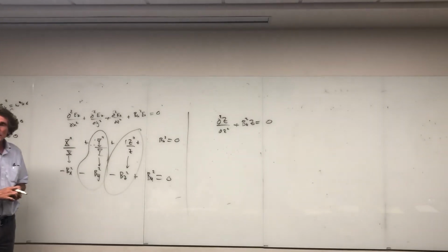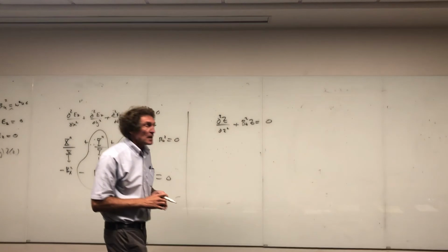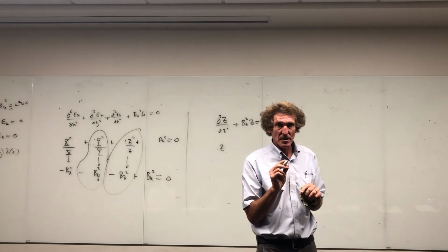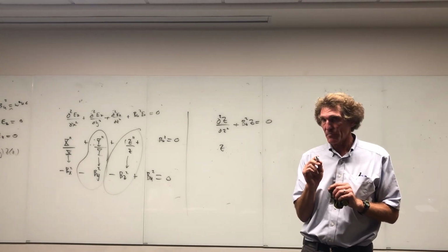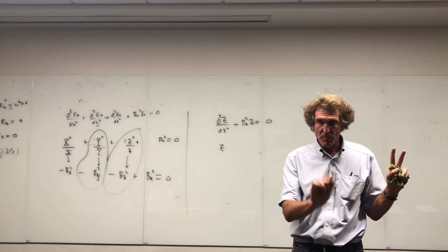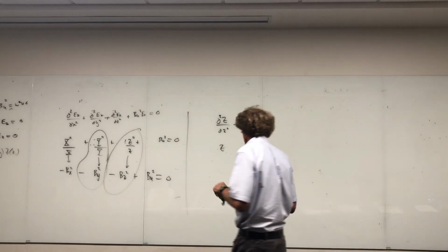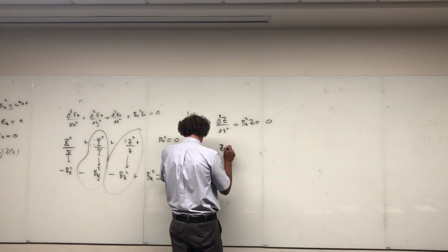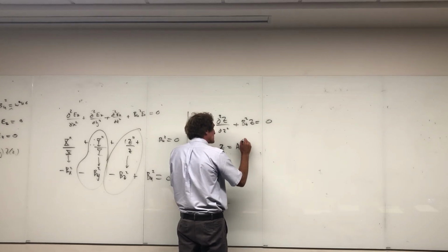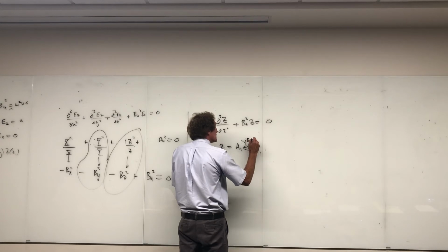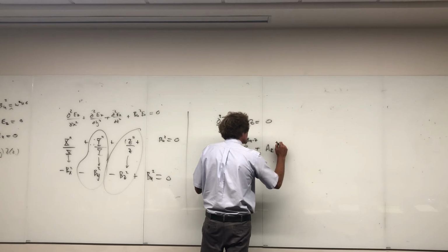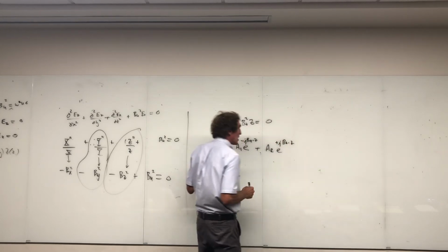Now for this one, this is in the direction of propagation. What happens is your function of z cannot be a sine or a cosine. It has to imply propagation. It could, in general, be that, but it would be what's called a standing wave. Here, we want to allow propagation in plus or minus z. And the form of the solution of this one, this is a legitimate form, becomes z is equal to some constant a1 e to the minus j beta z times z plus a2 e to the plus j beta z times z. Are you with me?